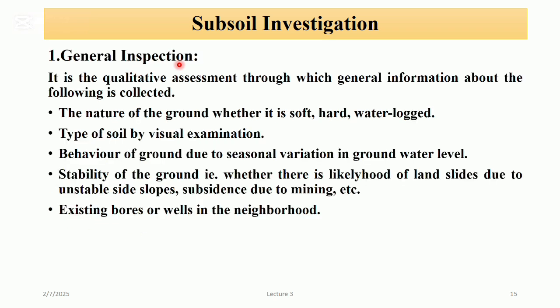General inspection. In this method of subsoil investigation, a study is made of all neighboring quarries made in the nearby areas for construction purposes, and of existing structures along with their foundations. The study of strata exposed to view in the old trial pits and unlined wells in that area may reveal the nature of soil at different depths.